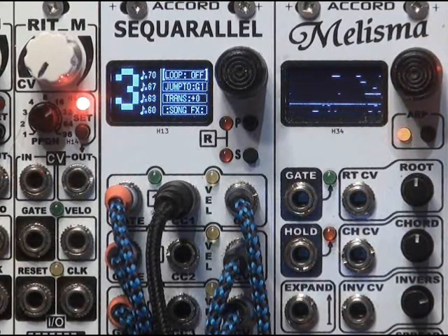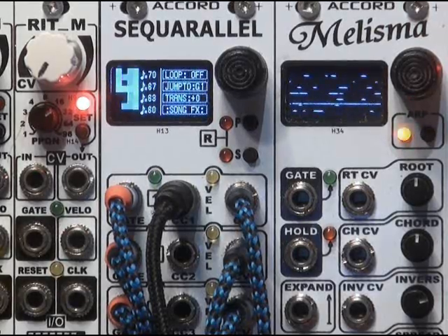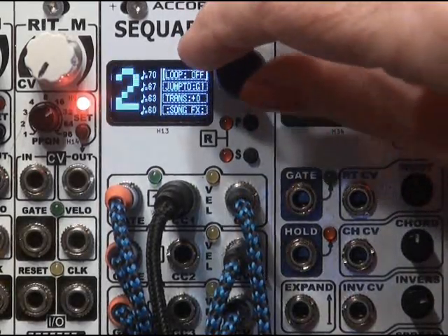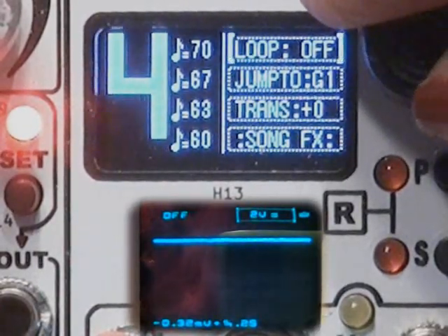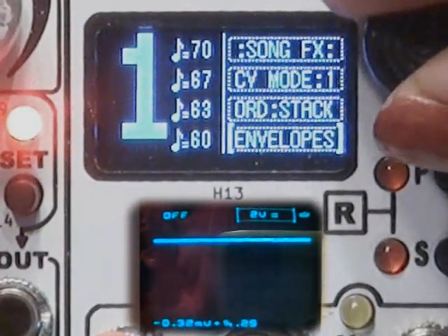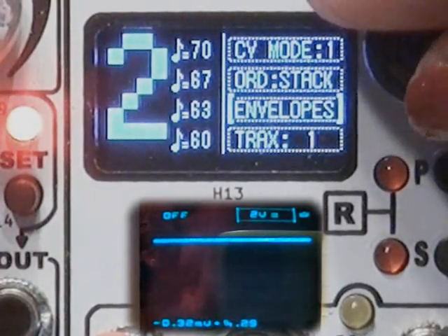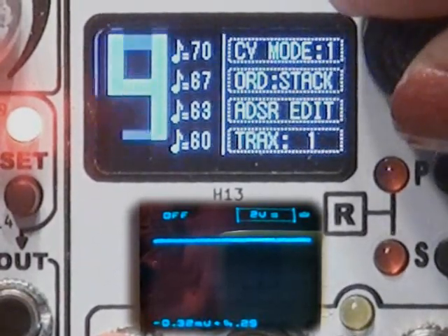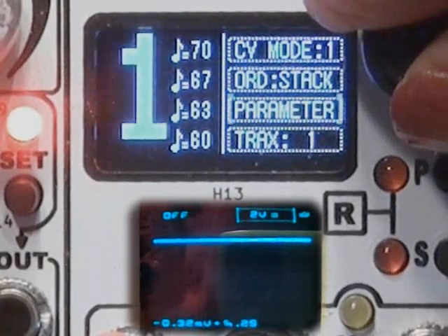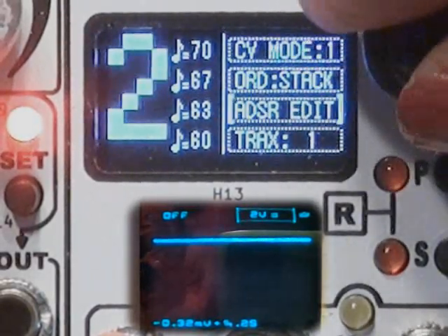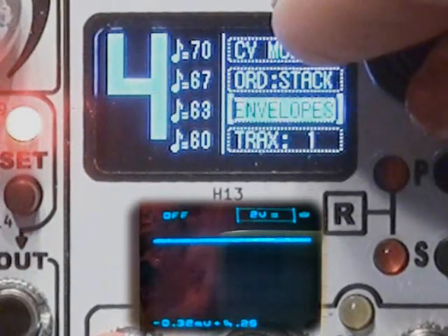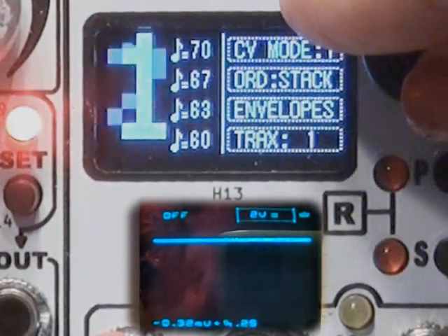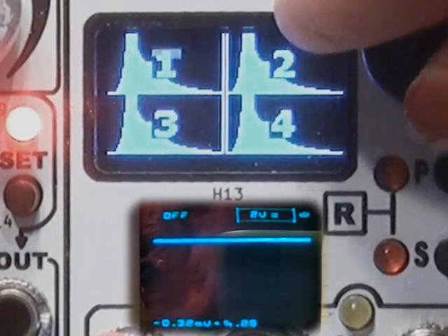Each song project can have up to 4 envelopes to output on jacks CC1 to CC6, as well as control a Midi CC, pitch bend, or aftertouch parameter. The envelope quick box acts as a drop-down to select envelope type: ADSR, draw by recording a CV input, or parametric settings. Holding on the envelope quick box will access envelope parameters and direct send options. The envelopes are shown graphically to select one for editing.